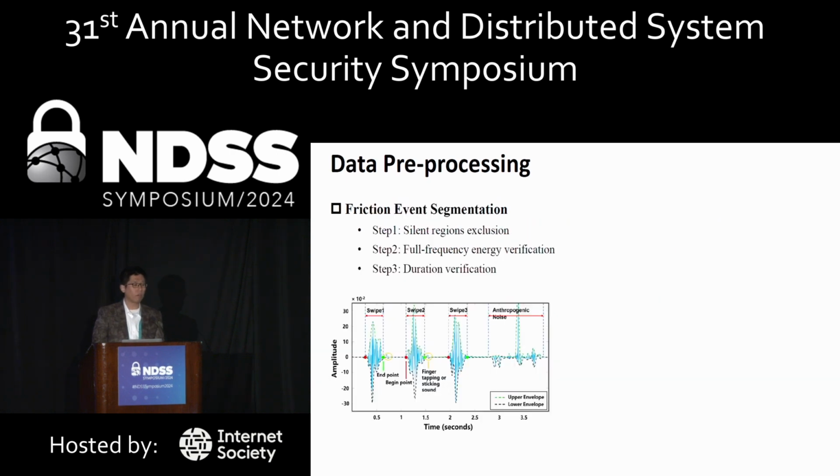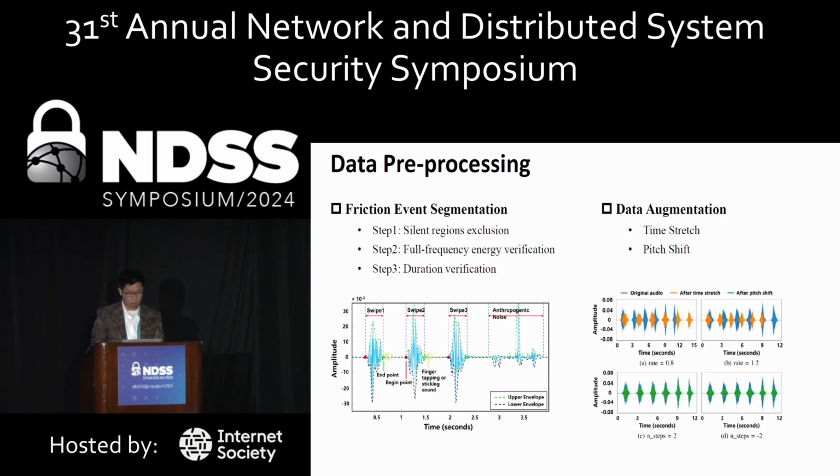Next, about the frequency segmentation. Here, we actively extract the very specific frequency sound segment from the audio and try to exclude the redundant information. We design a frequency event localization algorithm based on the frequency spectrum of the audio. We analyze the signals across the entire frequency range, and then we try to localize such sound events.